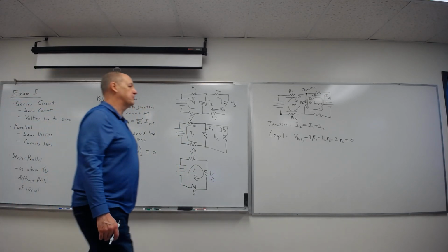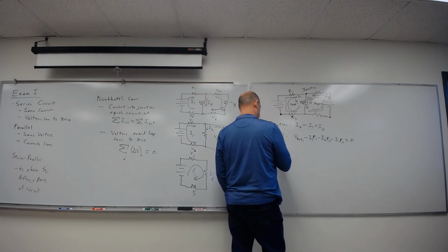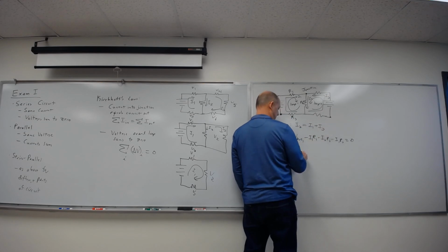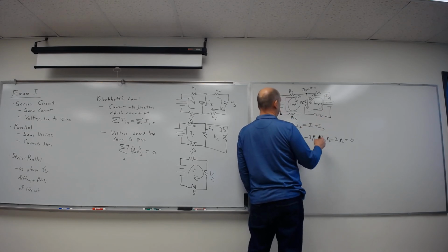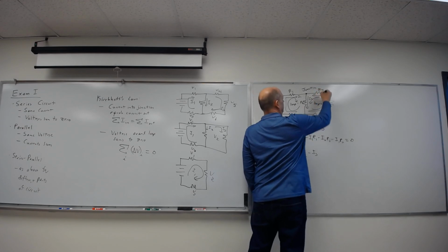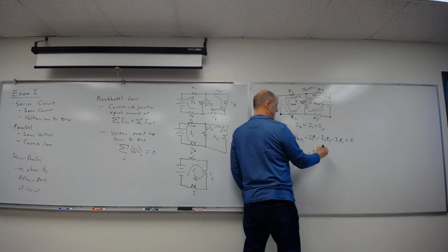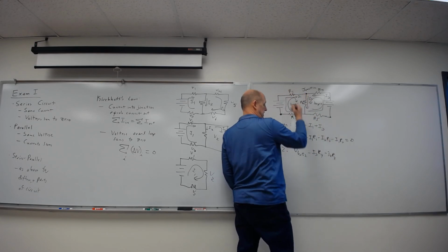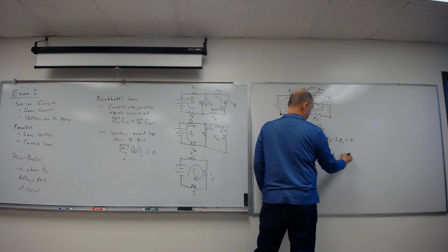And then I would come over here on this one and do the same thing. I'll start right there at loop 2. Go up. So that's my second battery. Subtract current 3 through, let's see, R3, cut off R4 and R5. Subtract this. Yes, that is the same voltage drop as here because you're doing the same. Subtract this, which is I3 R5.